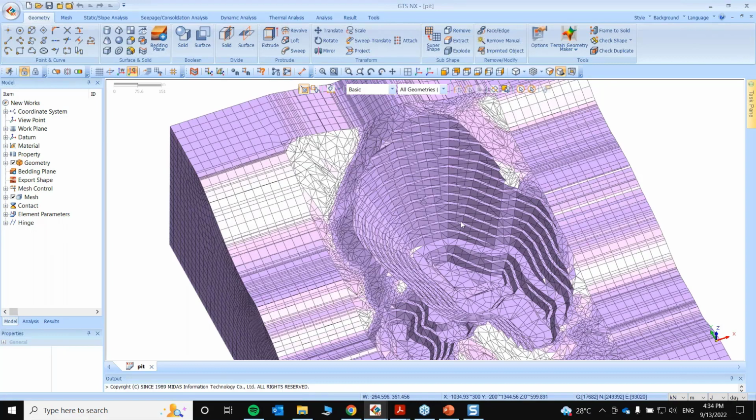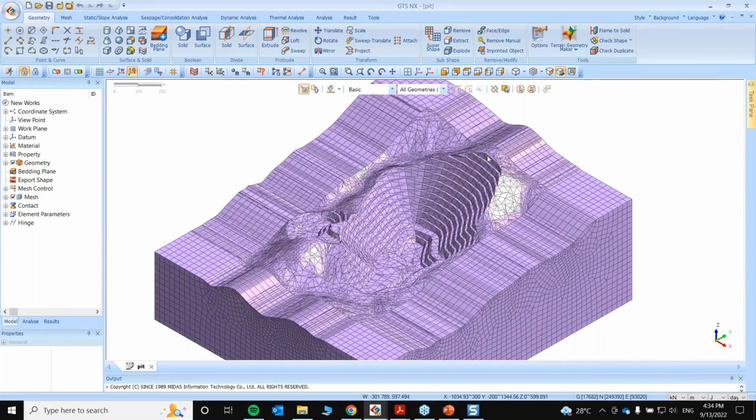Yes, because your FOS will determine how you want to proceed with the mining. The life of mine, or LOM, extends according to how you have planned your excavations and at the same time how you have designed the benches. Both of these should go hand in hand, otherwise you might lose on your extraction, that is the economic aspect, or you might lose on safety, as you can get a slope failure if you have designed your slopes to be too vertical.